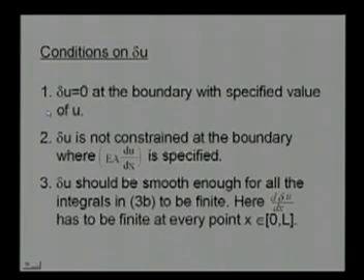Second, we have not put any condition on delta u at the end x equal to L. That is, at the boundary where the force is specified, E A du/dx for example, in our case at x equal to L, we will let delta u or w be free. They can take any value that you wish.